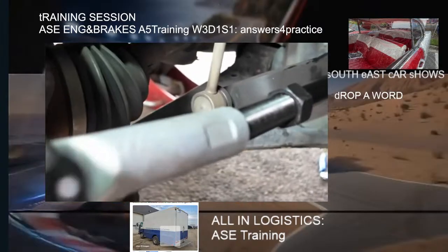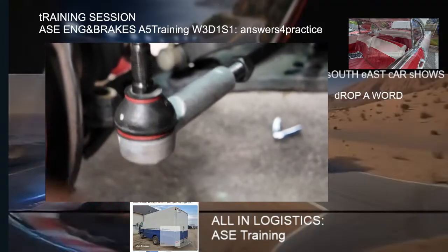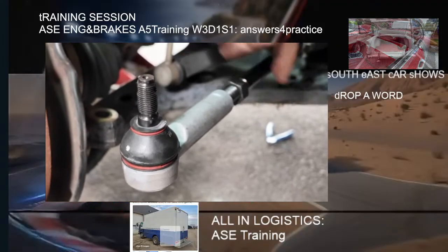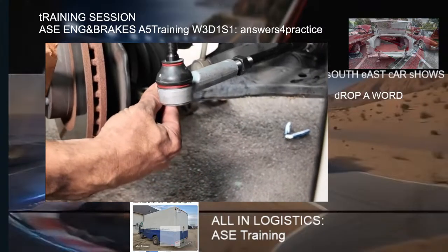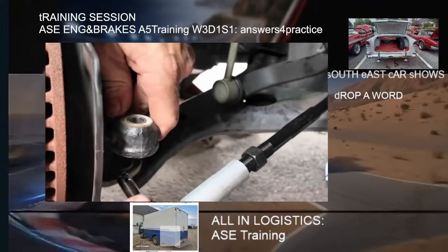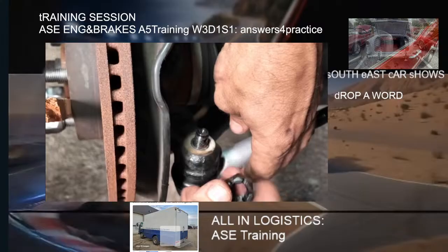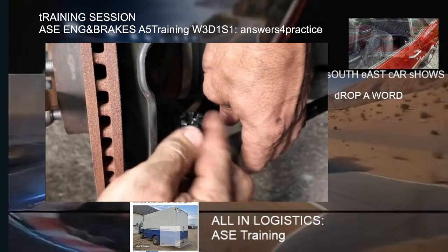Now I'm going to screw on the outer tie rod. So I'm doing it roughly the turns that I took it out. I'm going to reinstall it into the hub here and see how close I am to my marks. It's a lot harder when this stuff is new because these are really stiff. Okay, I'm gonna put the new nut on, just a couple turns so that it doesn't fall out.